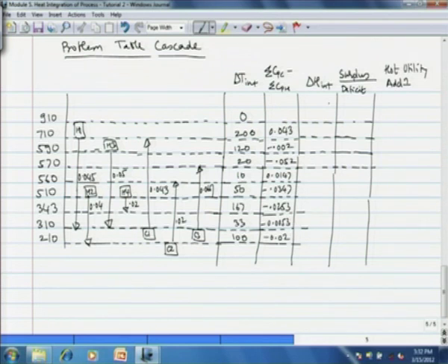So, that is summation CPC minus summation CPH, and when we multiply by delta T interval we get delta H interval. So, those values I am going to write now: 8.6, minus 0.24, minus 1.04, 0.15, 1.74, minus 4.23, minus 0.18, minus 2.